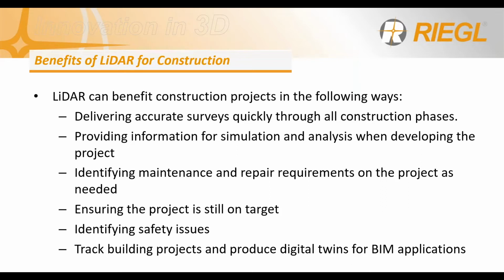With this, we're essentially allowing ourselves to create as-builts of projects, validating the current conditions so that we can effectively and efficiently conduct our pre-work. We can model our data so subcontractors can prefabricate pipe, conduit, and ductwork to speed up field production. We can solve problems that may have been unforeseen until we did the scans and correct incorrect as-built data.